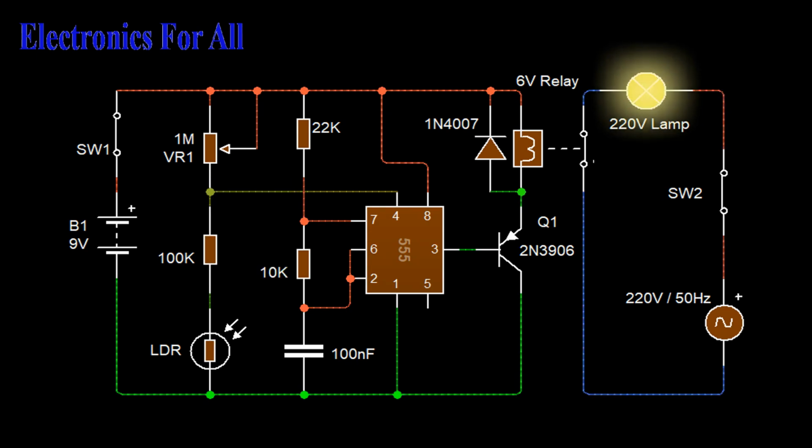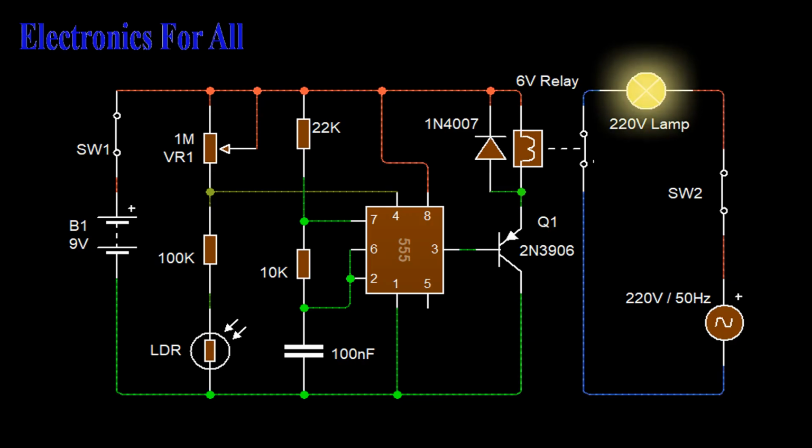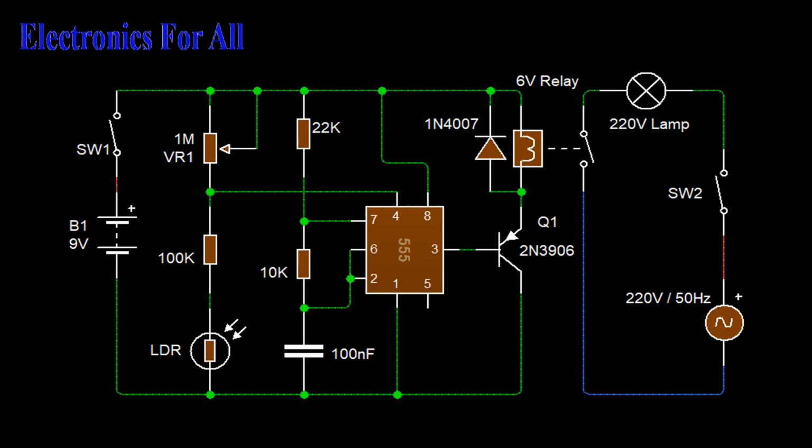The trimmer pot is adjusted to create enough resistance in the top branch of the voltage divider to drop almost all the potential, +9 volt, in the top branch itself. This leaves a virtual ground at the middle of the divider, the reset pin. Since the reset pin of the 555 is low level triggered, the timer IC will be in reset mode continuously, and so there will be no square wave output, as it should be. From this we can conclude that in the presence of light the 555 IC will be in complete reset and provides no output.